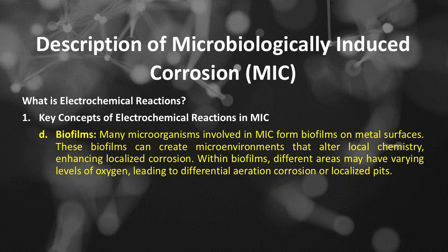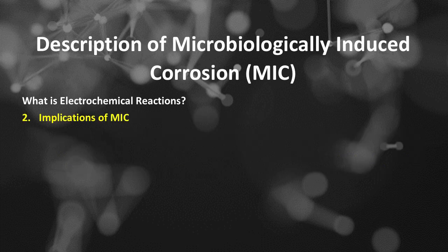Number D, of key concepts of electrochemical reactions in MIC is biofilms. Many microorganisms involved in MIC form biofilms on metal surfaces. These biofilms can create microenvironments that alter local chemistry, enhancing localized corrosion. Within biofilms, different areas may have varying levels of oxygen, leading to differential aeration corrosion or localized pits. Number 2 is implications of MIC in electrochemical reactions.